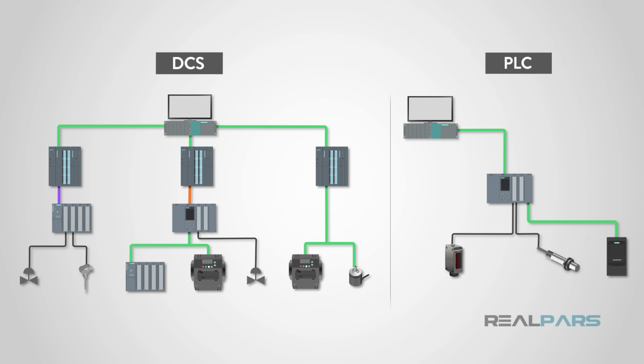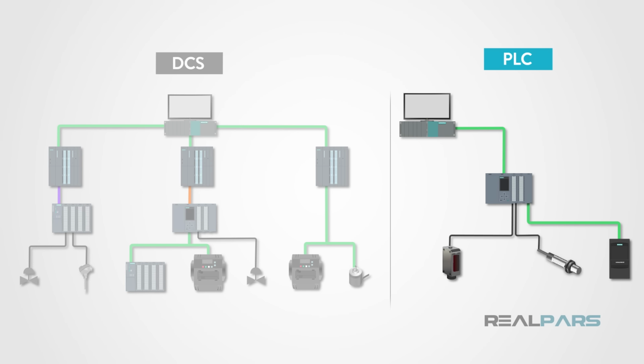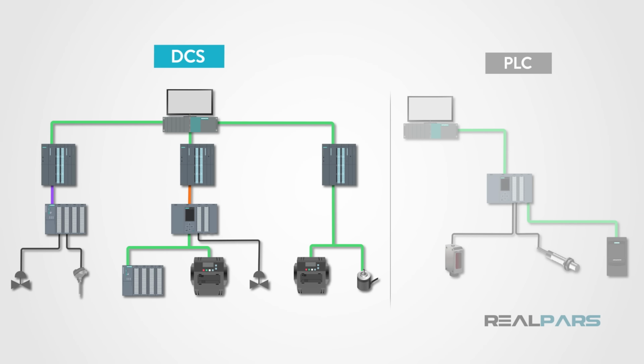In short, both PLCs and DCS have their place in the market today. PLCs would work best in a small production environment where component failure, if no redundant system is deployed, is a small risk for the application. The budget is restricted, or the tasks and I/O count are minimal. A DCS would be better used in an environment where there are large I/O counts, with many continuous processes. A processor failure in one section of the plant is not a problem for production, or risk assessment has determined that an integrated package would be the best option.